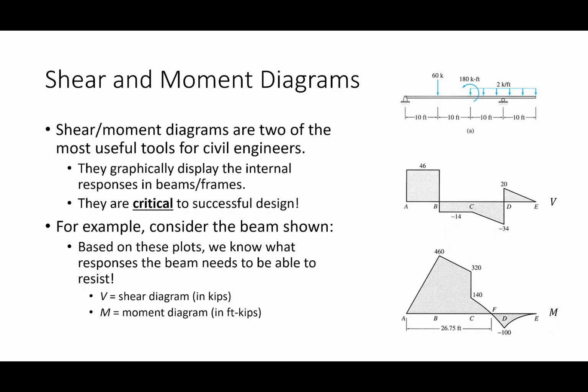Concrete is a material that behaves very well when it is subject to compression. When it is subject to tension, it behaves very poorly. Concrete in tension has a strength that's about 10% that of its comparable strength in compression. In fact, what we do to counteract that is we place rebar. Specifically, whenever we're looking at beams, we primarily place rebar in the beam wherever there's tension. That's reinforced concrete design in a nutshell.